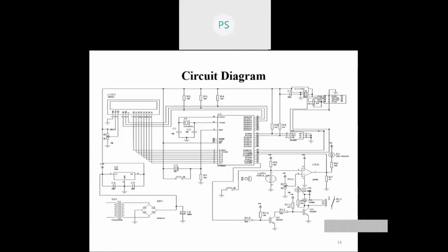The program executing in the microcontroller is responsible for monitoring the status of the IO pin where the sensor output is connected. When the IO pin goes low, it increments the counter by 1. According to the manufacturer of the energy meter, 32,000 pulses equal 1 unit. When it counts 32,000 pulses, it increases another memory variable, unit, by 1. For experimental purposes, we have taken 10 pulses equal to 1 unit. After getting a new pulse and calculating the unit, the microcontroller sends data to the LCD to display the current state.